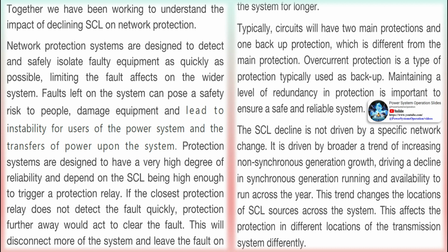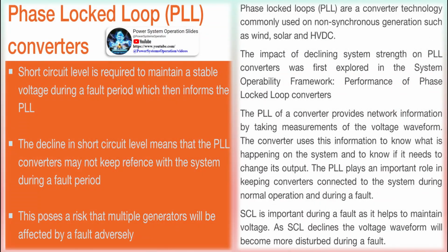A short-circuit current can be very large. If unusually high currents exceed the capability of protective devices like fuses, circuit breakers, etc., it can result in large, rapid releases of energy in the form of heat, intense magnetic fields, and even potentially explosions known as an arc blast. The heat can damage or destroy wiring, insulation, and electrical components.